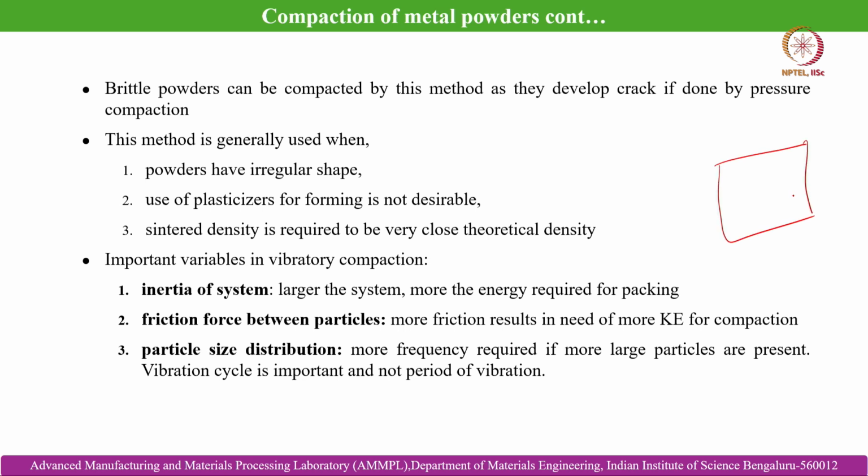over a vibrating table, and because of the continued vibration it facilitates arrangement of the powder particles in close spacings to each other, and it also ensures connection between the powder particles, which serves as the locations from where the densification gets started at the onset of sintering, and also it can facilitate uniform density distribution in the sintered parts with minimum presence of porosity. So that is why vibratory compaction is useful for brittle powders.